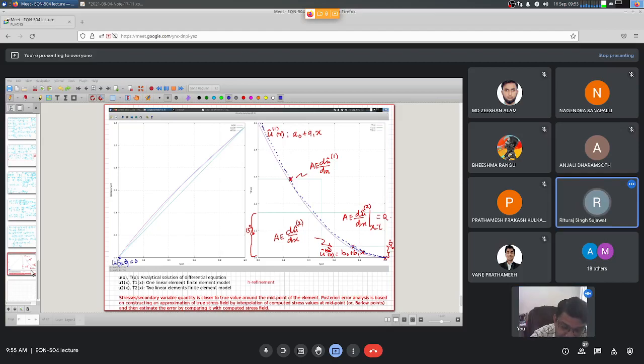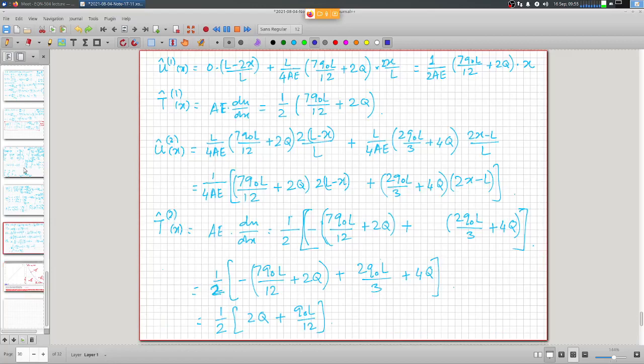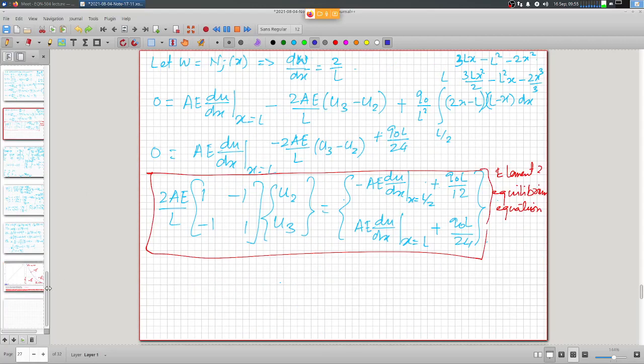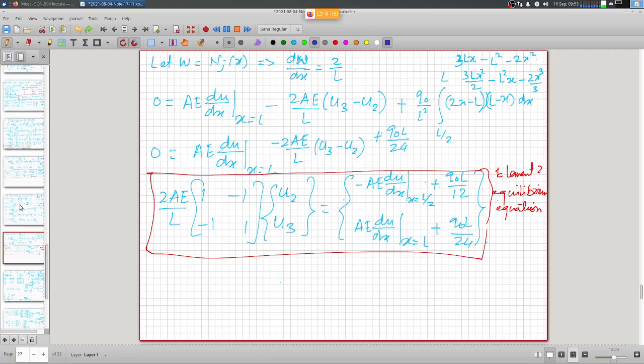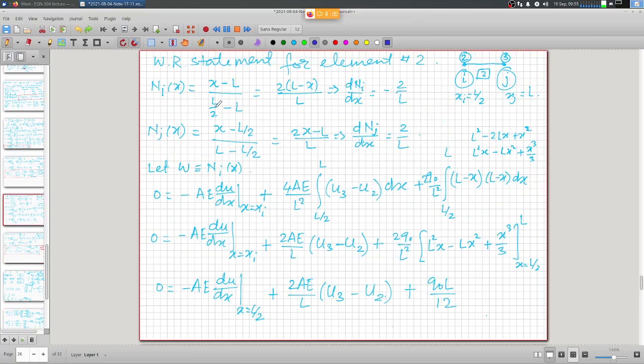This is how the calculations are done in the finite element software also, like they are taking the weighted residual statement and the simulation they are performing that. All this is already built into that. So for finite element solution, what you do is essentially you start finite element solution from, let me say, this is already known. When you choose the element and you define the geometry, then as you can see, these are defined by the coordinates of these nodes.